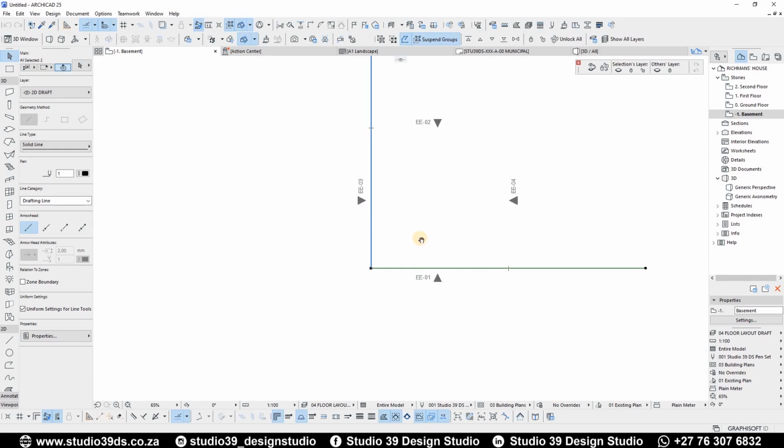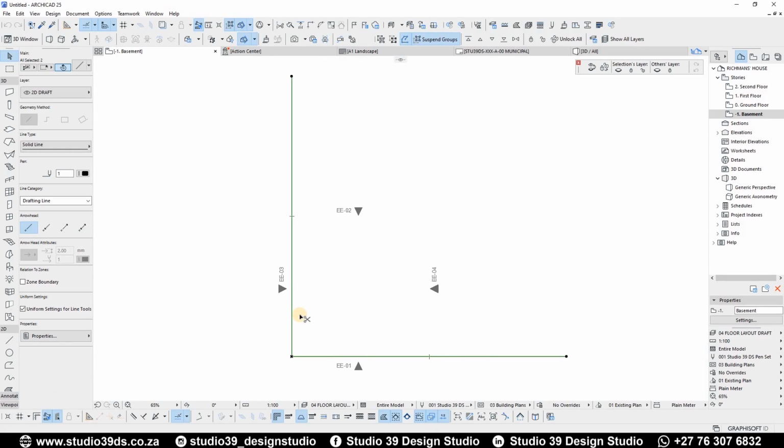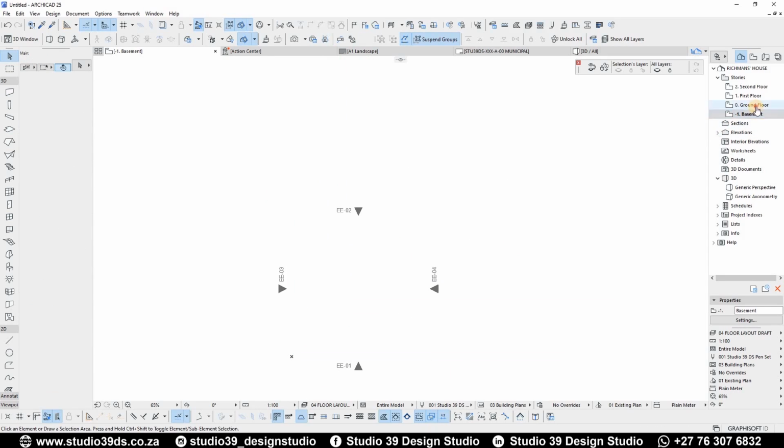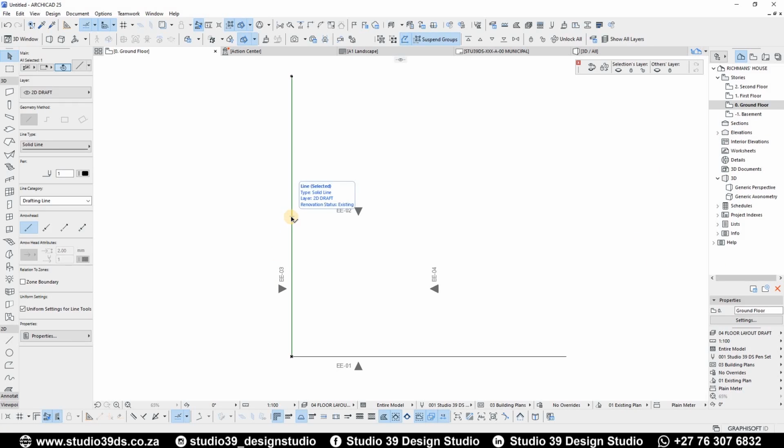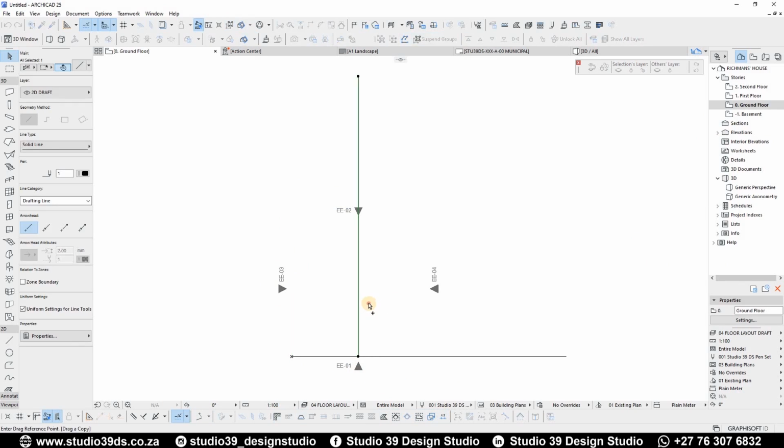With that said, let's get on with the tutorial. Firstly, start by setting out your workspace for a smooth and hassle-free environment. Starting off with the center line and offsetting it 4 meters on each side, meaning the stair will be 8 meters wide, and then the landing for the ramp will be 1 meter on each side.